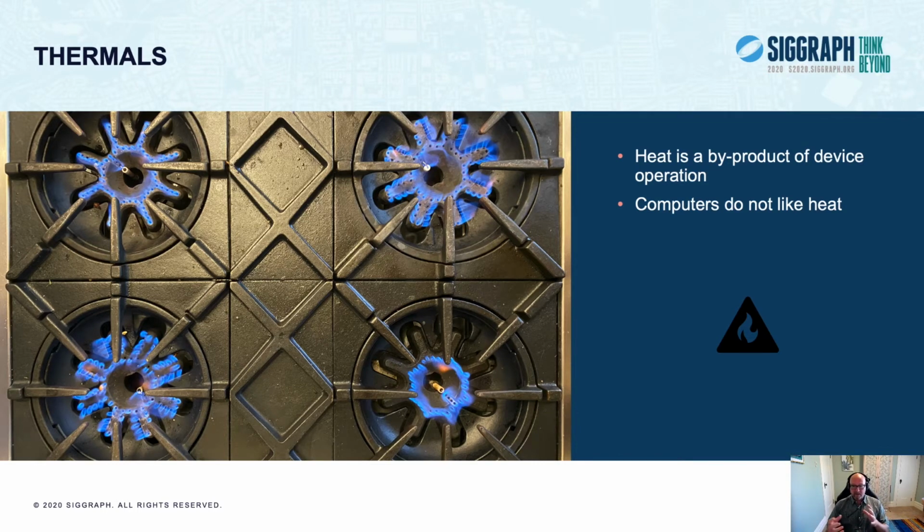Mobile devices, again relying on passive cooling, have to constantly monitor these thermal conditions, and then adjust the voltage and frequency of various portions of the chips that are either too hot or drawing too much power. This can, of course, have a huge impact on the behavior and performance of the software on the device. For example, if your CPU is all of a sudden running at half the clock rate that it was running at a moment ago, a lot of your performance goes out the window.